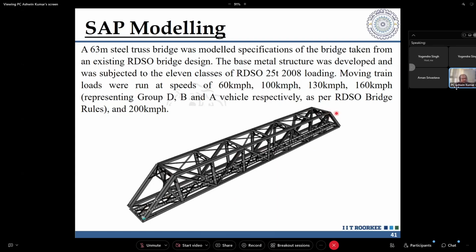You need to identify that. If you identify it, then you can limit your diagonal member fatigue assessment to that particular kind of member, and do your assessment using any finite element software. I mean, you have to go to the nitty gritty, right?